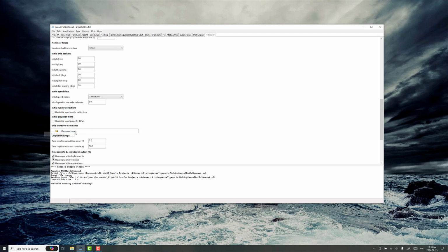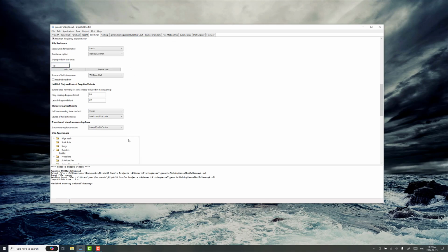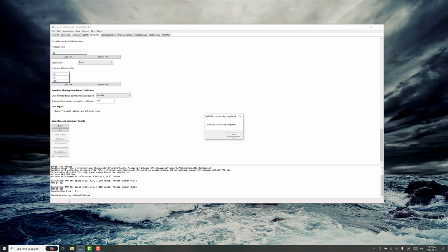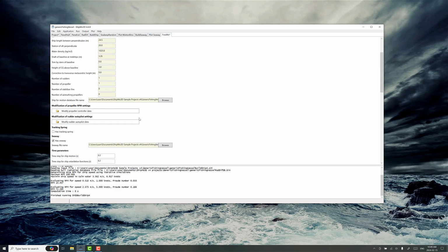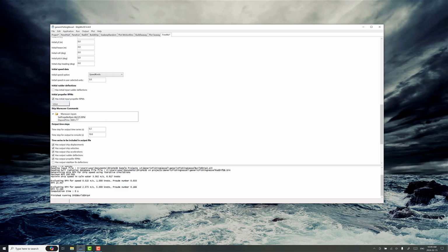Now we need to set some maneuvering inputs here. We can run it for an hour of time, which is going to give us lots of information. Basically, set propeller RPM. You can get some guidance on what that corresponds to. There is a way to do speed control, but sometimes it's just really nice to set an RPM and let it go. When you're in build ship, note the output. You can see it in the output if you just click run, and it'll do an evaluation depending on the speeds that you want. So you can see for 5 knots, it's 72 RPM. It might be going a little bit faster than 5 knots in those conditions. Anyway, we've got 125 RPM. Initial RPM is also good, but once you've got it in the maneuver command, all is well.